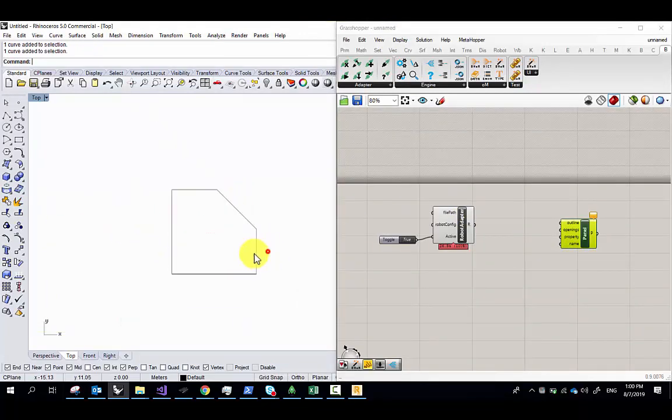So everybody follow along here. Create some sort of closed line curve in Rhino, just like CAD. And everybody let me know when you have that, a closed curve. It should be about 1 meter by 1 meter. Doesn't need to be, but let's make sure it's not 1,000 meters by 1,000 meters. Lily, good?